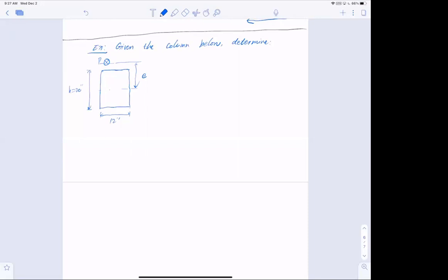For the reinforcement detail, I have 4 number 9 bars. Matter of fact, let me move the sign here to the center. You don't have to, but I just want to put it here because it looks more legit. I don't want to create another bending moment in the other direction. So I have 4 number 9 bars, and I have hoop stirrups going around it, like so.